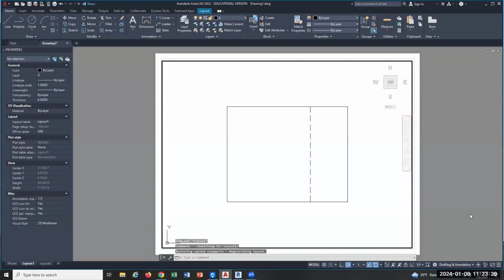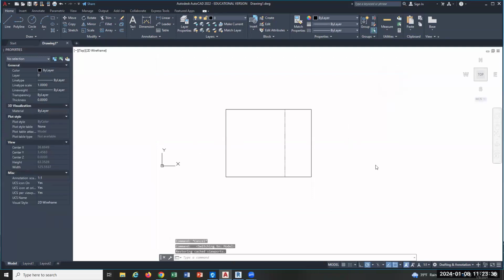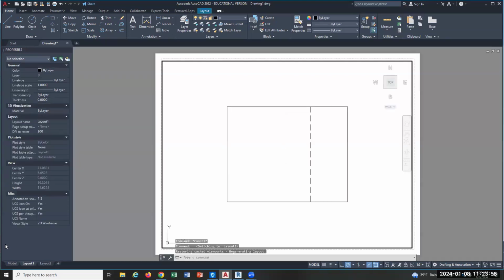Make sense? All right. So remember that once you get your drawing done, you want to get it done here first. So if there's multiple views, you want multiple views done before you figure out scale factor and before you do dimensioning. You don't want to dimension before you know the scale. Okay, so get your drawing finished. Before dimensioning, go to layout, set your scale factor. I have it set 1 to 5, and I like it.